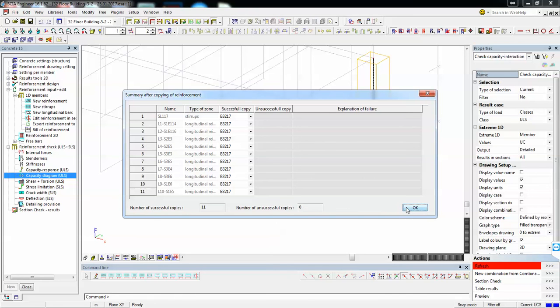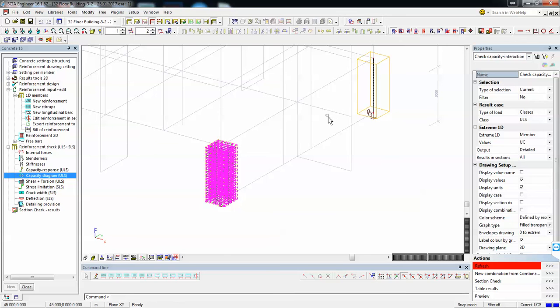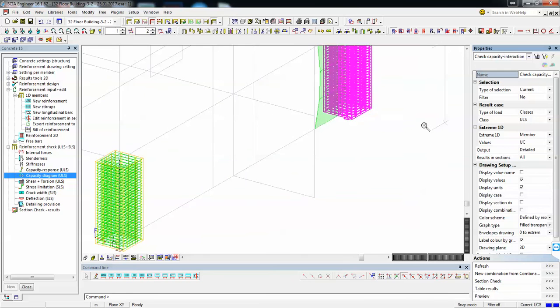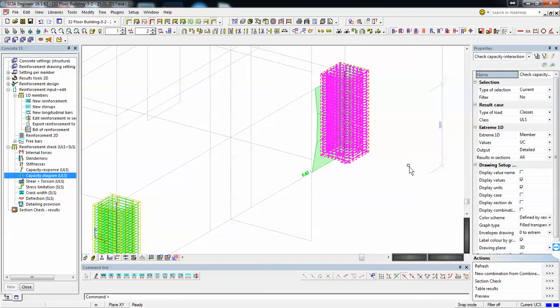Some columns disappear, I know, in your model, but mainly you'll do like this. You first establish the base cages, and then you go upwards level by level, and you can check them, so you make sure that everything checks okay. You can either work on all your columns like this, or analyze the diagrams and see which have the biggest forces on them. It's up to you if you reinforce all your building. Of course, the program might run slower if you do this, or you can choose the most relevant columns.